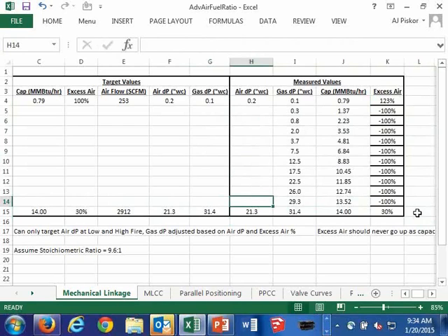So when I go through and I measure the air differential pressure for this application, it's going to gradually increase up, but it's not going to be increasing in any kind of a linear pattern. You think about my air damper, it's a butterfly valve. It's going to exhibit the flow characteristics of a butterfly valve. So it may be something like 0.5, 0.9, 1, 0.6, and then I'll just jump up from there, 3, 6, 9, 12, 15, 18, 20. So I don't know what those values are, and in fact, you won't know until you actually turn the burner on and then just measure what that air differential pressure is at these individual index points over here on the far side.